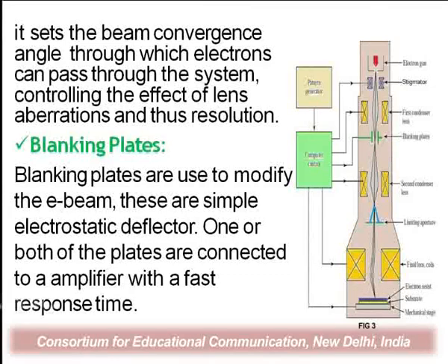In the previous photolithography techniques, we use masking techniques, but here in E beam lithography, we are directly writing on the wafer. There we use a mask to develop the electronic devices. Here we use the electron beam to develop the pattern on the wafer. Nano patterns can be developed on the wafer by using the electron beam.